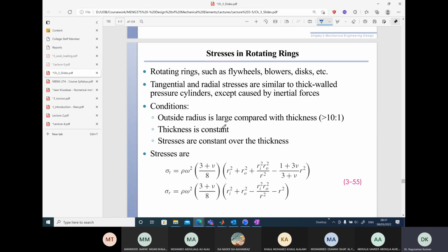There are also formulas to calculate stresses in the case of objects like flywheels. You have rotating flywheels, then we need to find, based upon the cylindrical coordinate system again, and based upon the speed of rotation of the flywheel, what is the radial stress, normal stress, and the tangential normal stresses. They are again found out by using the formula here.